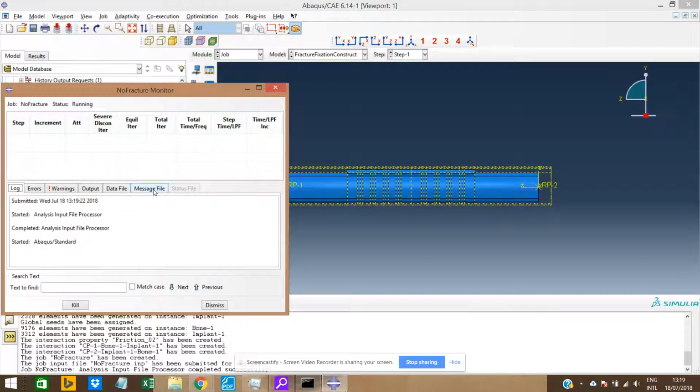Also, as you might have learned previously, generally the fewer elements you have, so the less dense the mesh is, the faster your simulation would be, because there are fewer equations to be solved.